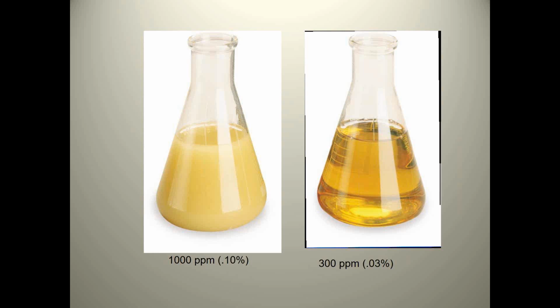Now, your mineral oils go through a process called hydrolysis. So the hotter the oil, the more susceptible the mineral oil is of mixing with water. So if you've ever pulled a sample like this and you want to know if your oils went through hydrolysis, if you let this sample cool, sometimes you can put the sample in a refrigerator. If it clears up after about an hour, it hasn't went through that change yet.